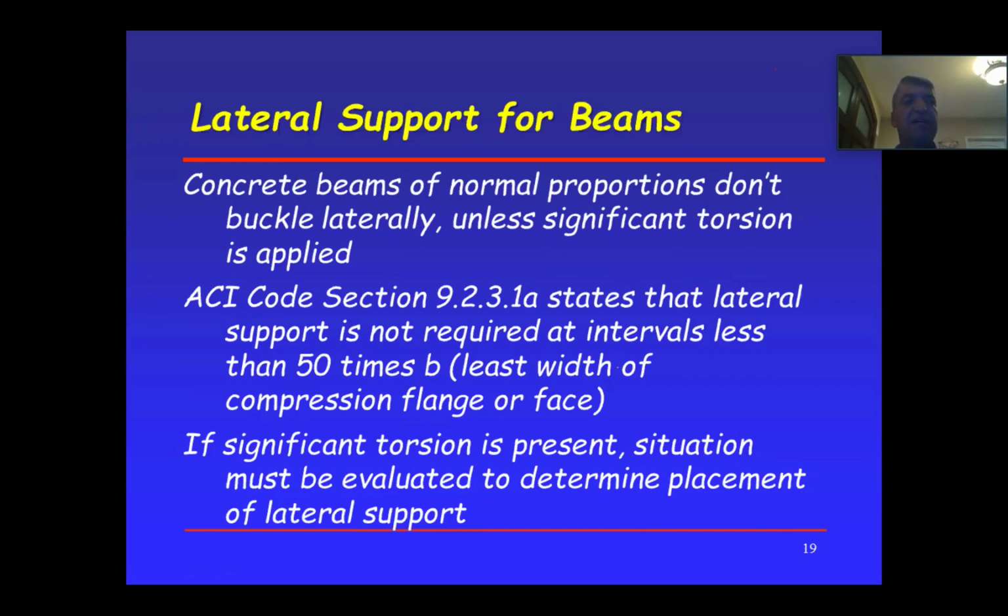Torsion is when you have a slab like this book I'm holding, and you have a beam on this side and a beam on that side. This beam is loaded only from one side, so therefore it's going to have a torsion to it. Remember in deformable bodies, I showed you a beam with a T along the beam. That's a torsion. It comes from the fact that this beam is holding a slab on one side only. But if the beam is holding slab on both sides, they're going to equate themselves, so there's not going to be a problem.